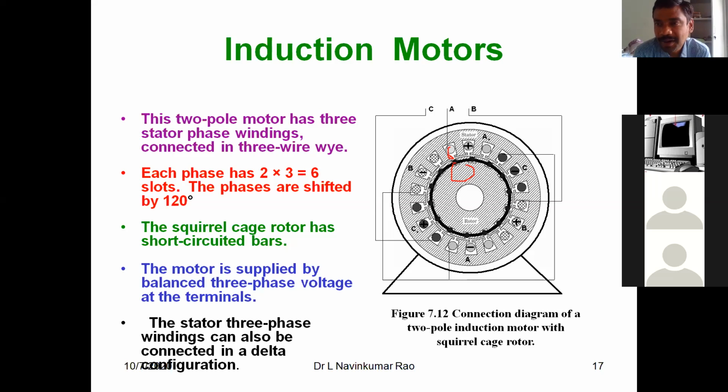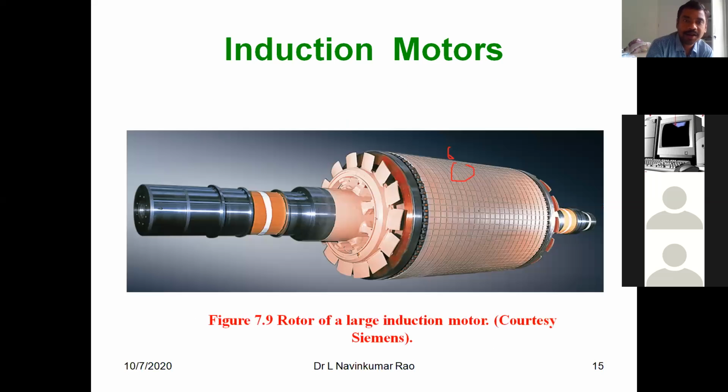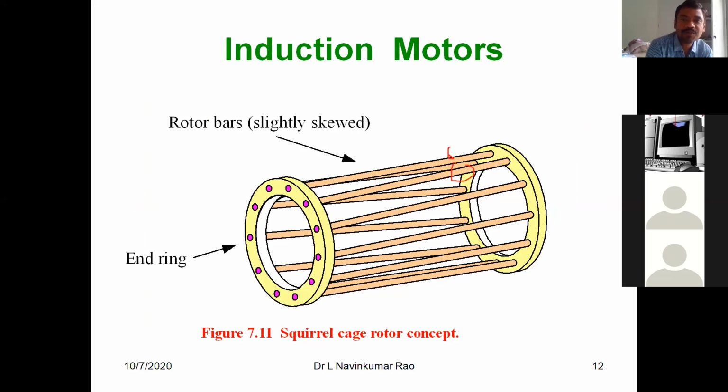There is no torque in a transformer. Now you can say there is a three-phase winding in a transformer. Why is the transformer not rotating? There is no two opposite forces. Getting my point? There is no two opposite forces to develop a torque. Two anti-parallel opposite forces develop a torque, which is not the case in a transformer. Therefore, the transformer is not rotating.